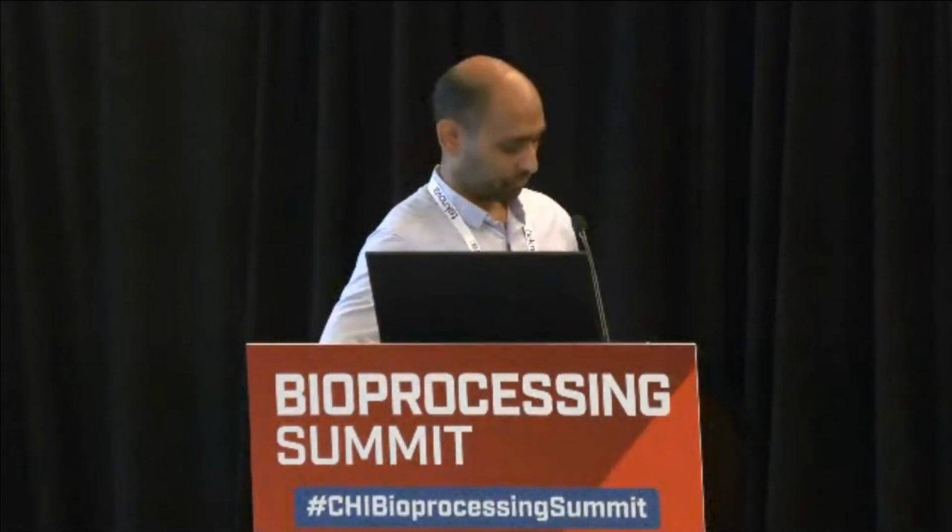I was curious about the modeling part at the end, this hybrid model that you're looking at. First, how many runs do you feel you needed to be able to start training it? And is this all fed batch? Do you have perfusion? My understanding, and I'm not the expert here, is that it takes about a couple dozen runs to train the model, with Ambr runs, Flex data, amino acid data, et cetera, to get the initial model calibrated. This is all fed batch Ambr 15 that we've trained on, plus a bit of 250 data.